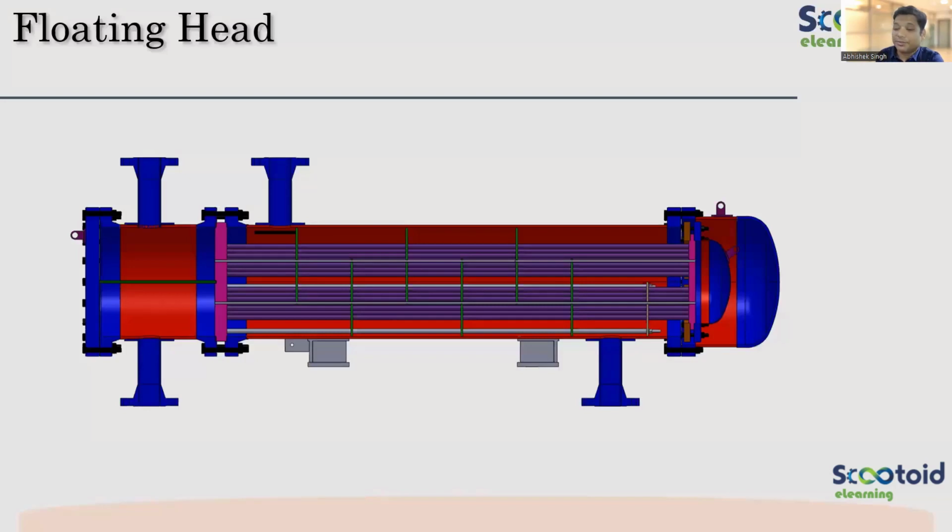There is no longitudinal baffle here. So you can see only one pass in the shell. So at least can we freeze the shell side? Shell side type is E. So most of you have absolutely got it right. What is the front? Front you have seen many times. Nothing but A. So A, shell type is E.